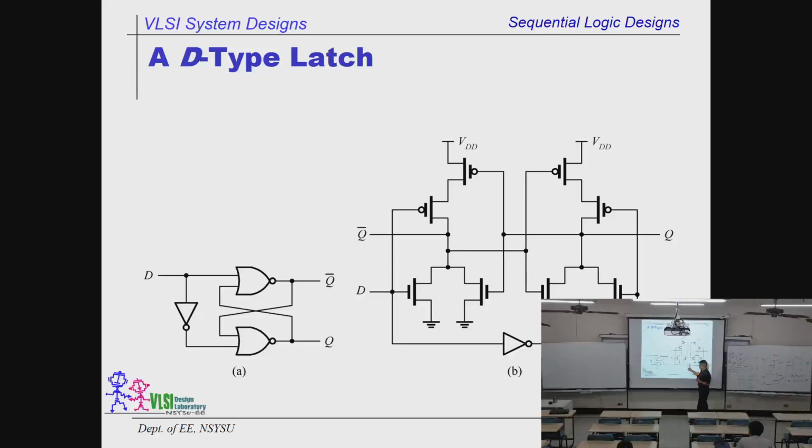And there is the inverter over here. So this design is the simplest design for students to follow. 10 transistors, that's all. And if you add these 2, that's another 1, 2, 3, 4, 5, 6, that's another 12. So a complete design will be around 24 transistors.